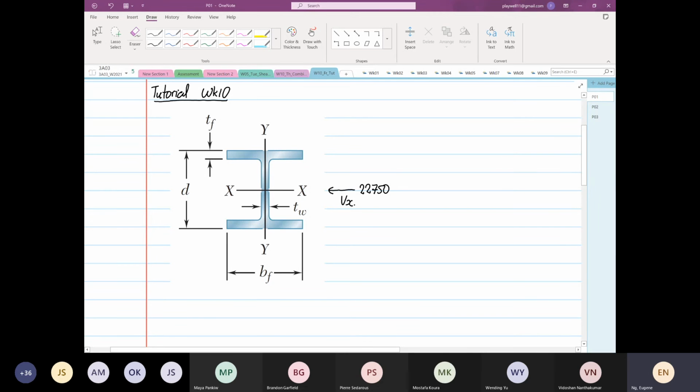So we're going to find the shear in xz is equal to shear in zx. So this is equal to Vx over Iyy, then we have Qy divided by t, right? So we already know what the thickness is, and the thickness value was, we had the thickness value.